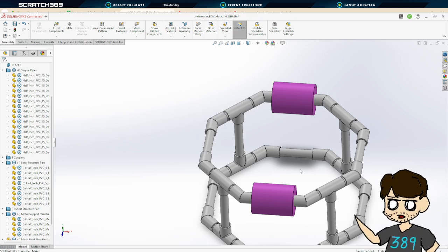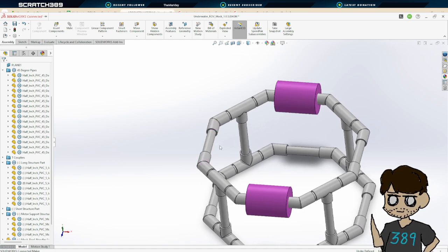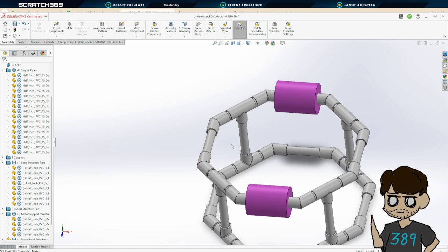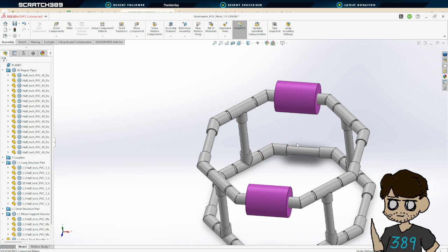How do I fix that indeed? Well, one solution would be, instead of having the motors off to the side of here, you would want the motor to be thrusting directly into the pole, so it's not inclined to push it, like turn it in any which way.